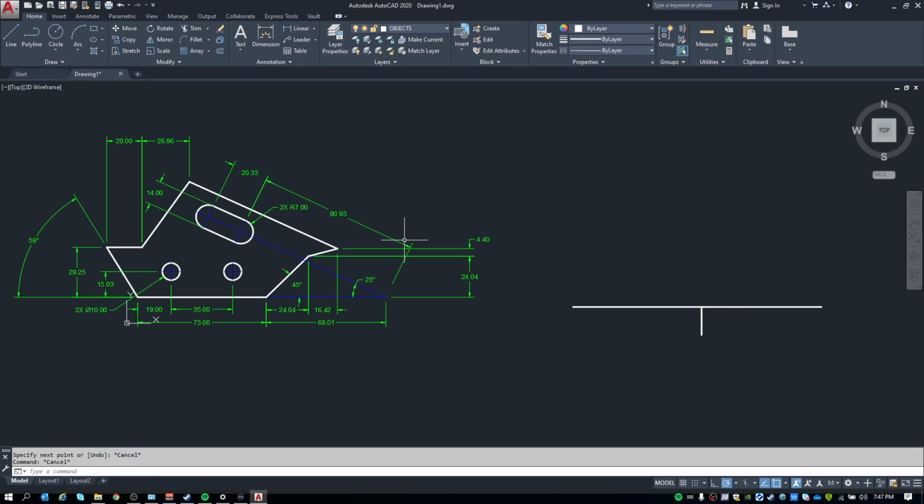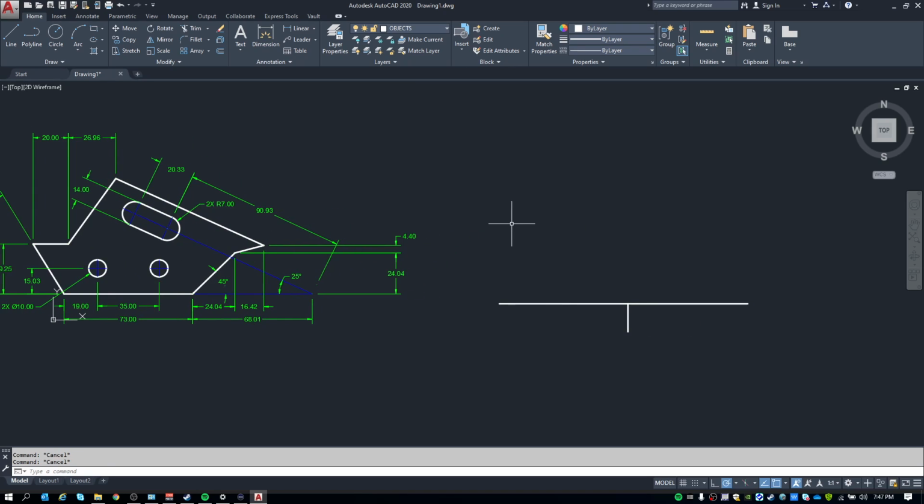Okay, so now that that's done, this is the next line we need to draw. It is given that it's 45 degrees. First things first, I'm going to draw this line and do the angle command at 45 degrees. Since from left to right it's going uphill, or it's got a positive incline, it'll be just 45 degrees, not negative 45. Then I'll draw it to whatever length, just longer than it needs to be, because I'll be trimming it up here in a second.